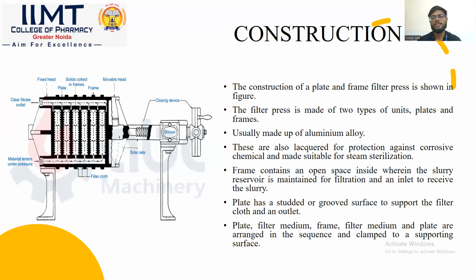Plate has a studded or grooved surface to support the filter medium and an outlet. Plate, filter medium, frame, filter medium, and plate are arranged in a sequence and clamped to a supporting surface. So this is the equipment.